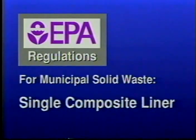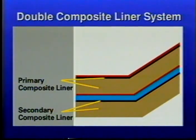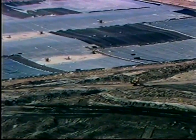The U.S. Environmental Protection Agency, EPA, regulations require a single composite liner for municipal solid waste. However, several states require or allow double liners for municipal solid waste. For hazardous waste, EPA regulations require a double liner where the secondary liner is a composite liner. When the highest level of environmental protection is needed, both primary and secondary liners can be of the composite type. Double composite liners are often installed for hazardous waste landfills in the United States.